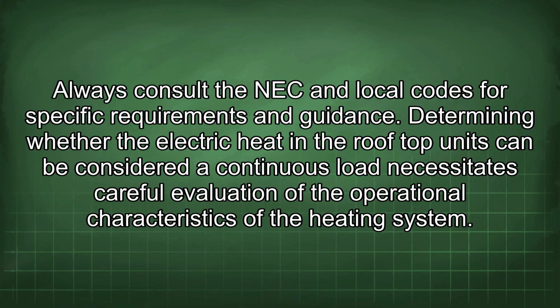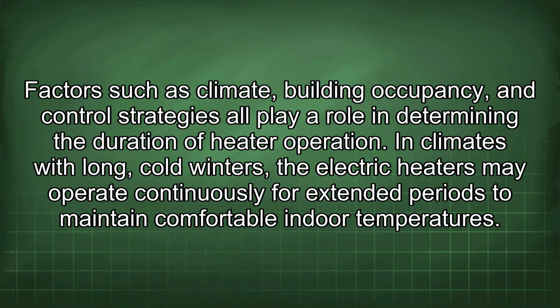Determining whether the electric heat in the rooftop units can be considered a continuous load necessitates careful evaluation of the operational characteristics of the heating system. Factors such as climate, building occupancy, and control strategies all play a role in determining the duration of heater operation. In climates with long, cold winters, the electric heaters may operate continuously for extended periods to maintain comfortable indoor temperatures.